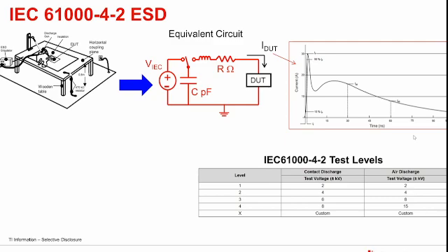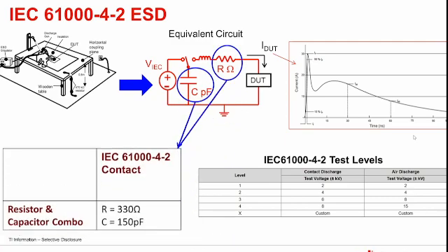So now let's get into the actual doing your job part of the ESD diode. The ESD standard has been defined by IEC 61000-4-2. This just means that you have a large voltage source that is discharged onto a capacitor and resistor made up here and gives you this current profile that you can see over here on the right.